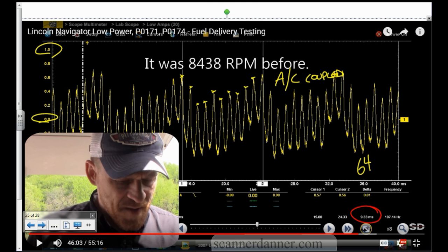Somebody do that for me real quick. 6,400 and what? 30. That's interesting. So if I would have known a little bit more about this system, I said somewhere between 4,000 and 6,000 is what I have listed in my book, though I did say some pumps run at higher speeds. Here's my before number. Here's my after number. The pump actually slowed down. My amperage increased. The pump speed slowed down.